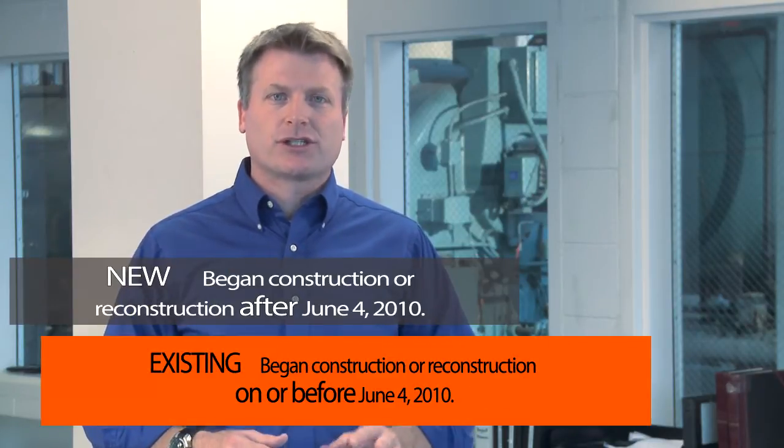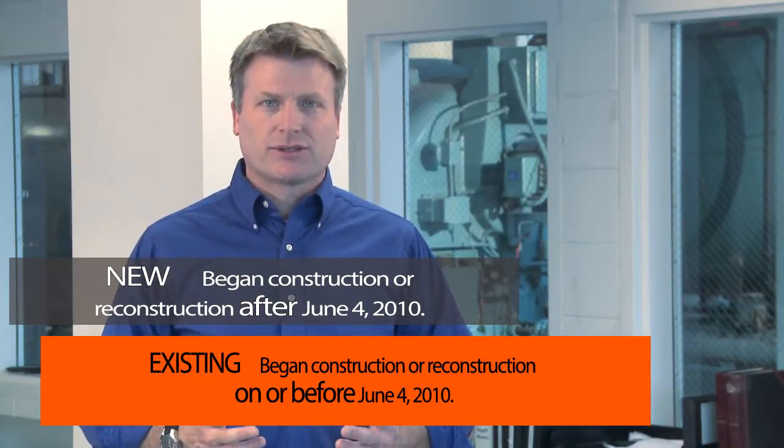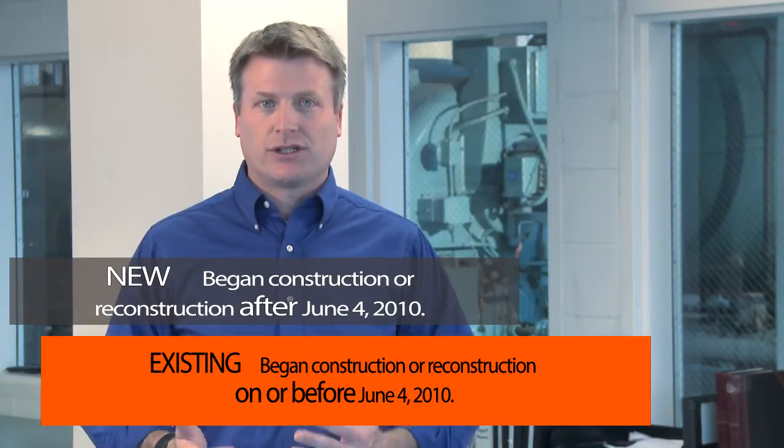Before we discuss those boilers subject to either the 2 or 5 year tune-up, let's define a new versus an existing unit. New sources are those that began construction or reconstruction after June 4, 2010. Existing sources are those that began construction or reconstruction on or before June 4, 2010. New sources are not required to complete an initial performance tune-up, but are required to conduct the applicable 2 or 5 year tune-up no later than 25 months or 61 months, respectively, after startup.